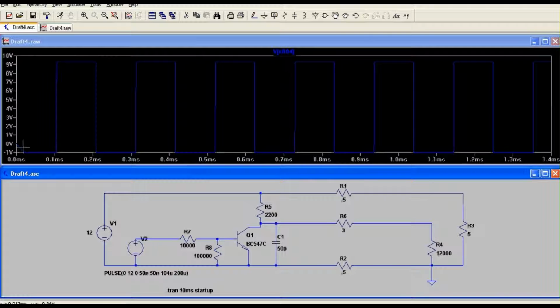But it's the actual voltage going negative here that I think in some cases could be a problem for the silicon receiver. So I'm not suggesting this is a very typical scenario. I'm just saying this is something that you might come across, and something to look out for anyway, something to consider. And it may not even be in this kind of scenario where it's on the end of a cable. This could happen on a circuit board by itself. It's possible. Okay.